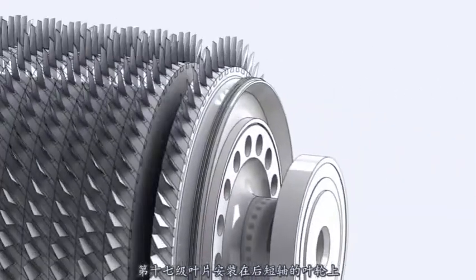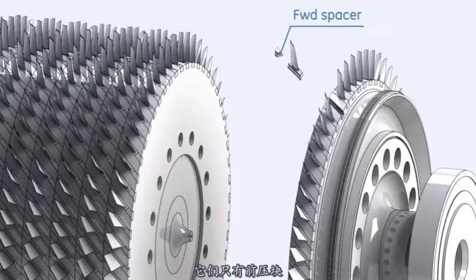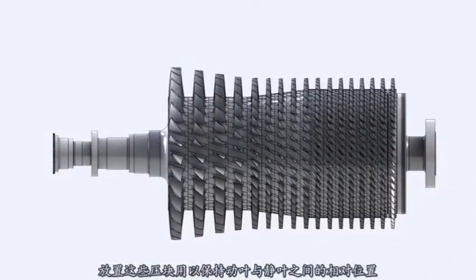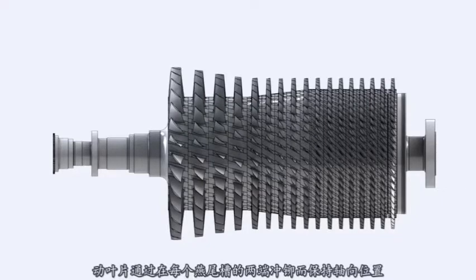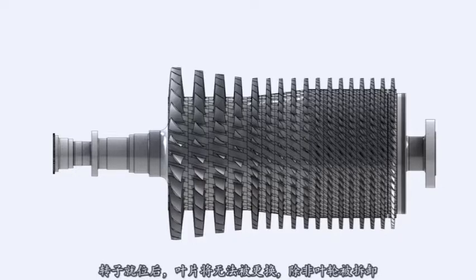The 17th stage blades are mounted on the wheel portion of the aft stub shaft, and they have only forward spacers. These spacers are placed to maintain the relative position between the rotor and the stator blades. Rotor blades are held in axial position by staking at both ends of every dovetail slot. Compressor blades cannot be replaced with the rotor in position.